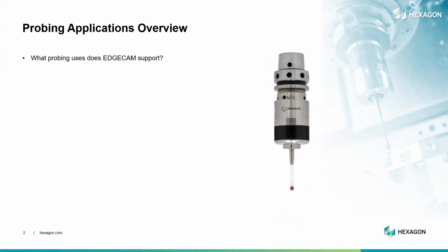So, does your CNC machine have a probe? These smart devices are widely available in many CNC machines. They can be used for a range of tasks. The most common usage is to assign or modify the work coordinate system. This is often done by machinists as part of CNC machine setup.